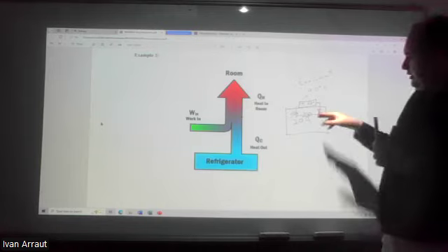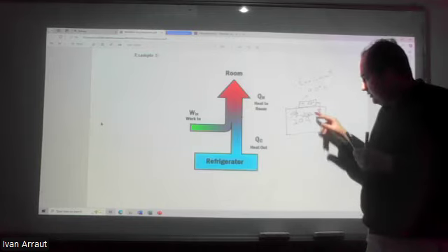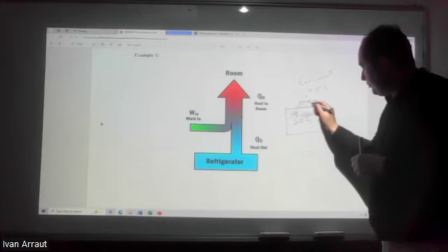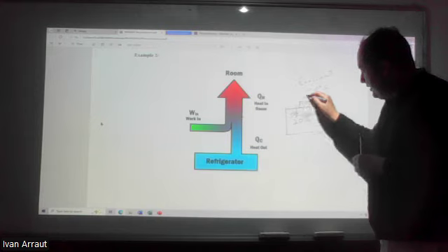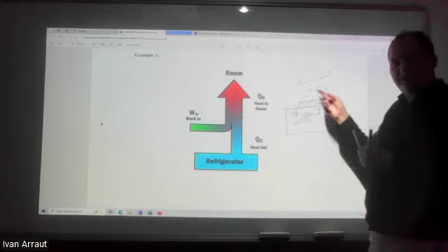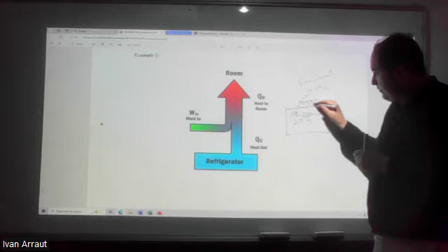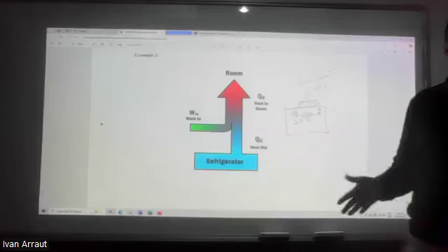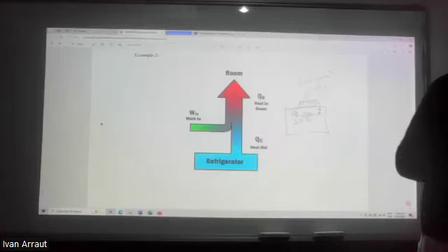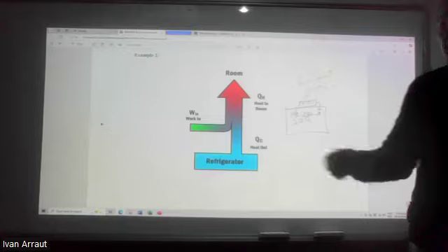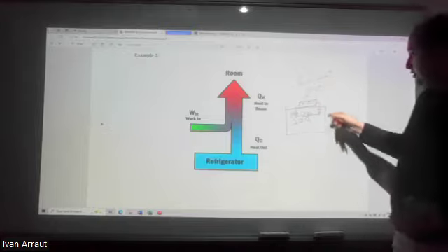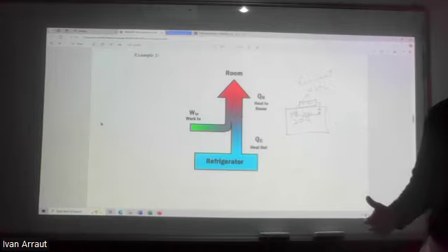Anyway, there is a liquid here flowing. The liquid here is very hot. Let's put that it's at 50 degrees or something. Then it emits the heat. The heat you collected from the room is emitted here. Then that very hot liquid has to relax. It's at a very high pressure. So it suffers an expansion here. A very huge expansion, which reduces pressure and reduces its temperature.